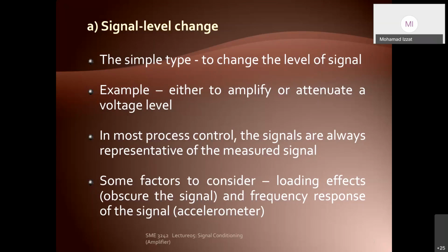When you put them together in satu block in sequence of 1, 2, 3, 4, they become a system of instrumentation. So as this thing is coming from different vendor, different manufacturer, different technology, different maker, dia punya properties ataupun dia punya features for this different system adalah berbeza. Okay, that's why you need signal conditioning system tengah-tengah untuk buat some kind of matching ataupun padanan daripada blok pertama to the blok yang ketiga lah. So saya mention signal conditioner dia blok kedua, dia tengah-tengah. So kerja dia buat matching.